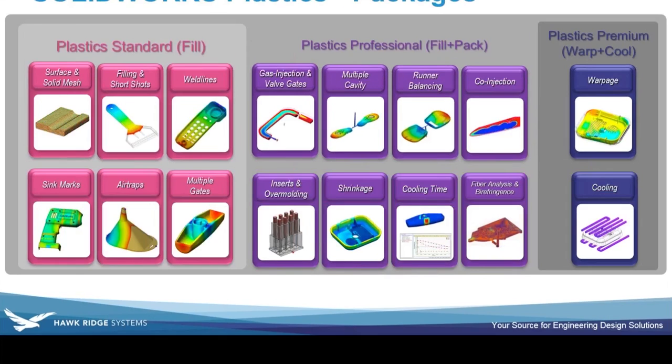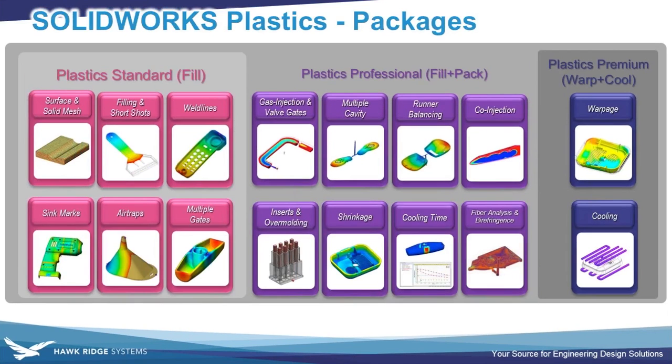Okay. So once we've checked those fill-related aspects, let's go on now and try to get into more detail about what the mold itself should look like and what the cycle time itself will actually be, both for packing and cooling. We all know probably that when you're making a part, the fill is not really the biggest component of the overall cycle time. Pack is typically just as long as fill, maybe longer, and cooling probably is the biggest time hog.